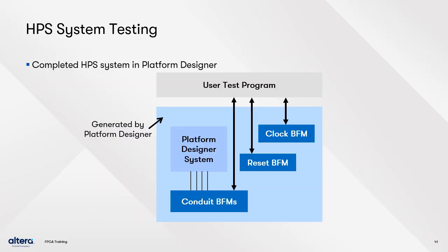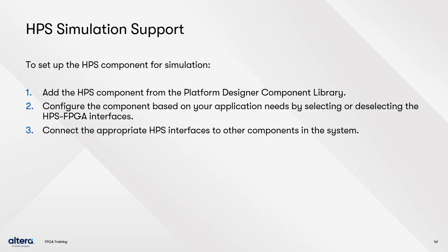If you're performing a system simulation, you can generate a system for test bench, and clock, reset, and conduit BFMs will be inserted to allow you to simulate the system as if it was interacting with outside components. Here you would control the BFM through the test program, and the test program will be used to simulate inputs and outputs of the system through the conduit BFMs. The HPS component itself is too complex to be simulated.